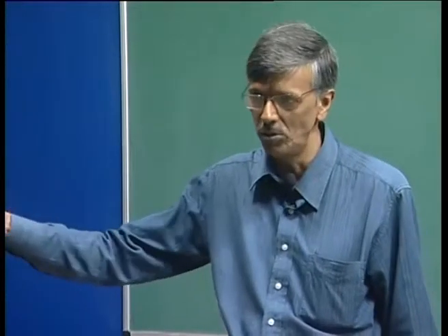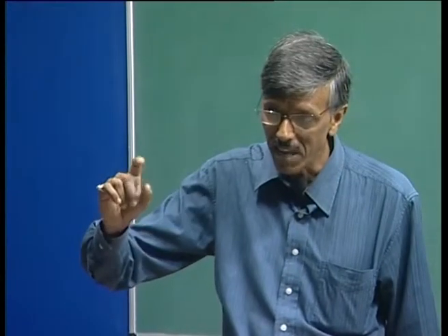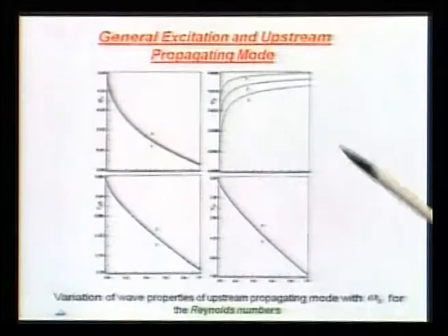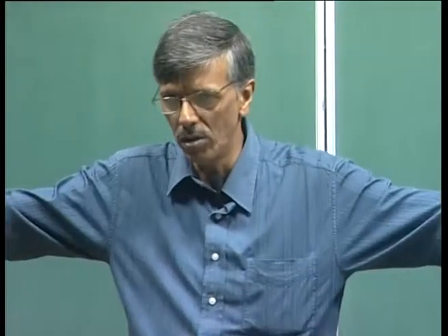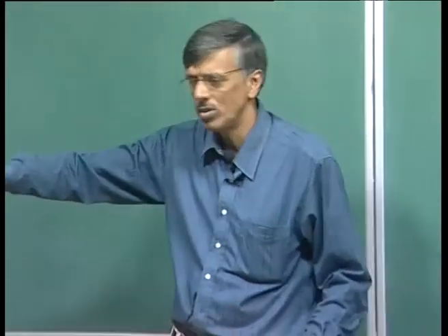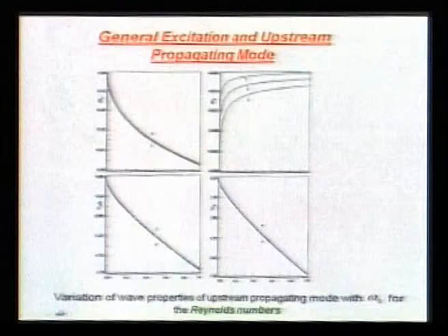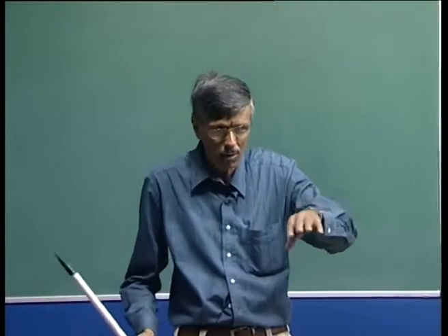But as you go to the later part of the boundary layer, where Reynolds number is increasing, this damping rate comes down, and you would be able to see those. This might tell you what Klebanov might have been seeing. If you take a wind tunnel of a very long stretch, you are going to simulate very large Re towards the downstream end, and there you would find that upstream propagating modes will be unstable.